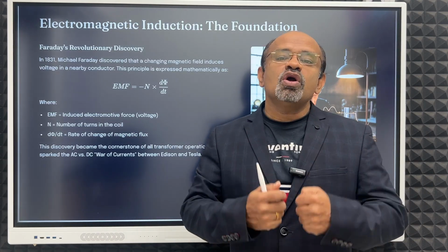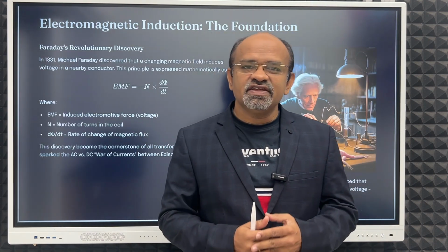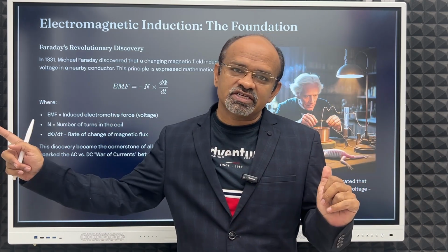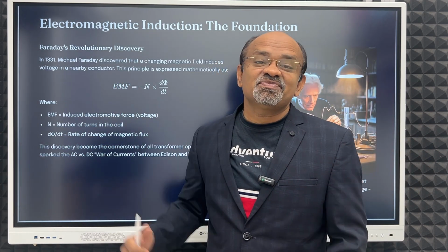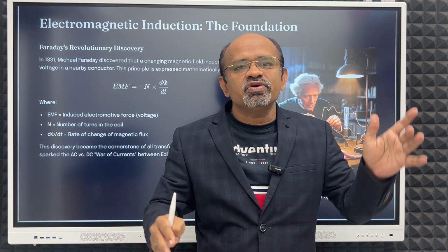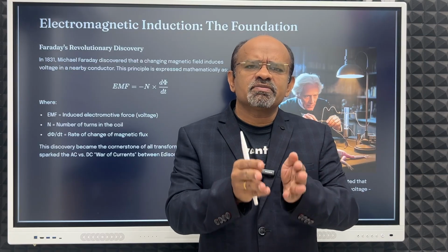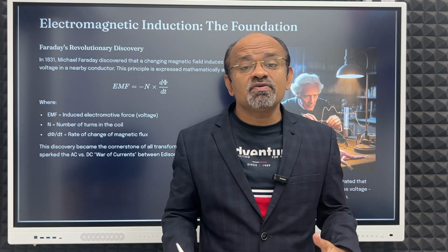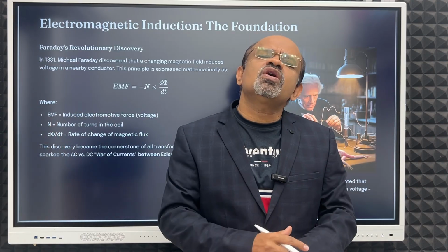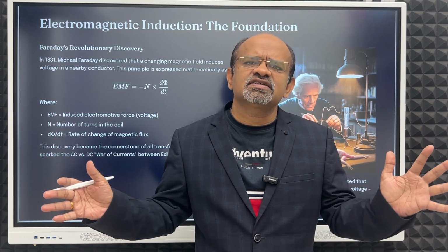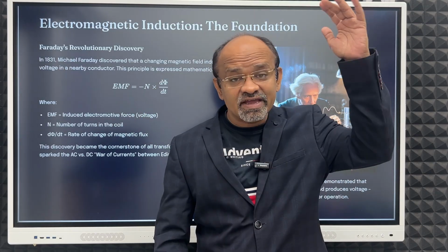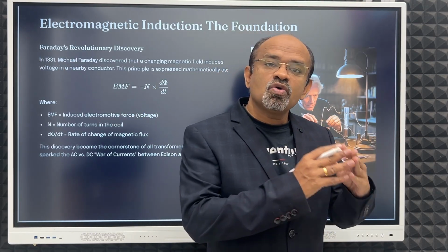Because if you want to transfer a huge amount of power from one location to another, as we saw in the last lecture, only this device, the transformer, helps, because it steps up the voltage, the current goes down, and we can easily transfer the power using a small conductor. Otherwise, huge current needs huge, big conductors, which is not even possible. Like we have seen with 765 kilovolt, that high voltage is transferred from one location to another.